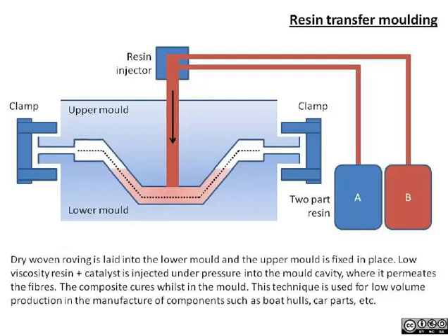So we could achieve a process very similar to a thermal injection molding for thermoplastics, or for permanent mold or injection mold casting of metals, except rather than a solidification process or a cooling process down below Tg, it's actually the cross-linking or the network polymer formation that's actually achieving the material properties.